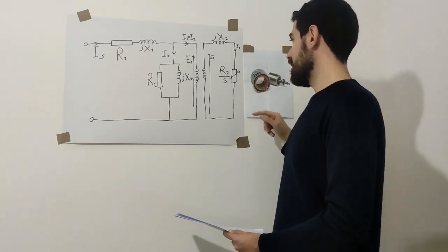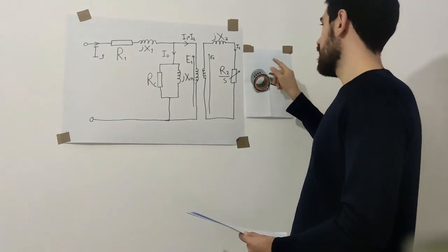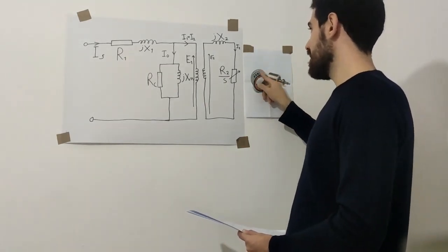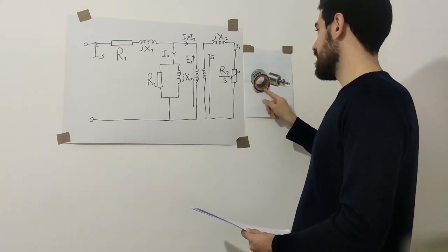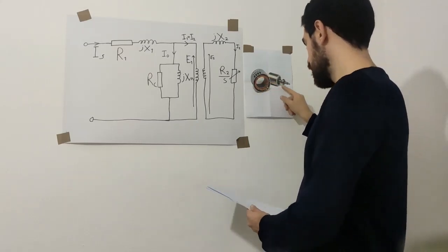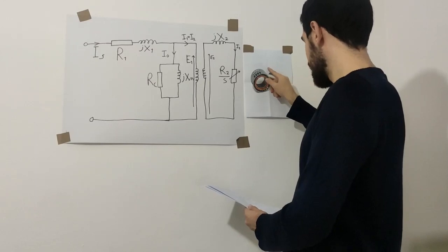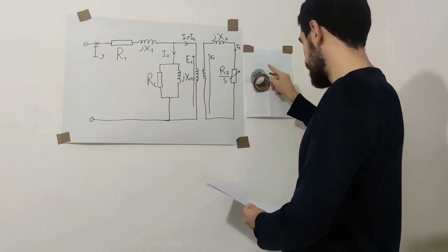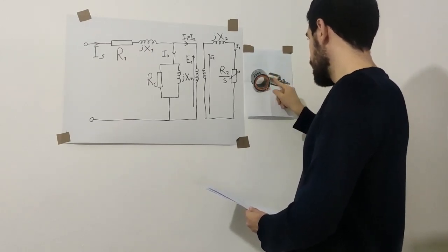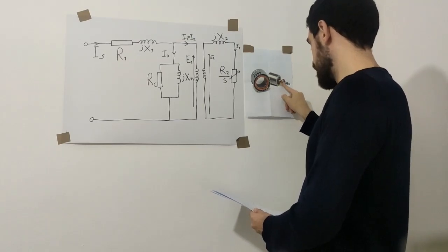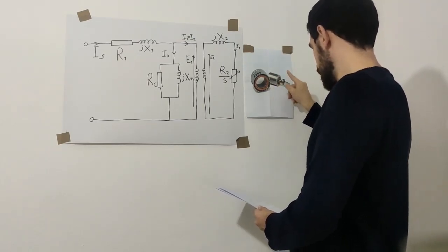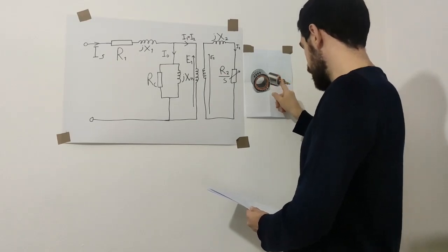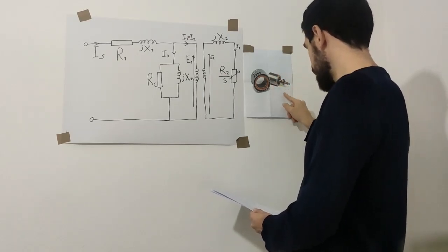The stator frame is the outer part of our motor, and it supports the stator core and stator winding. The stator core carries alternating magnetic flux. In the rotor, we have shaft, we don't have brushes, we have a laminated iron core, aluminum rings, and bars.